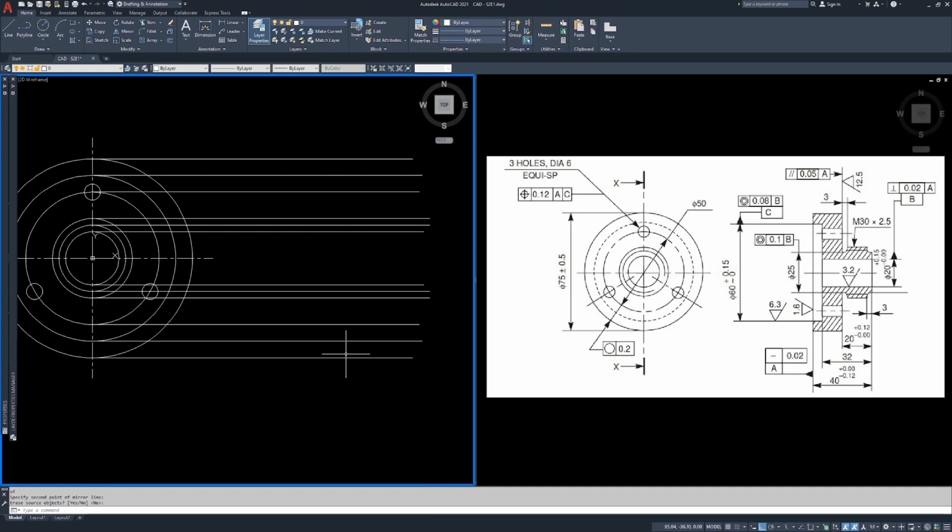So now, from these construction lines, we can actually build what we're seeing over here. So we need to start looking at some dimensions here. It looks like they're starting from the back. So all we need to do is just draw an arbitrary line in the back. Let's just draw a line just like that. L, right click, shoot a line back there. That's this back edge. So it looks like our first dimension in is going to be 3 units. So let's O, enter, or O spacebar, 3, enter. Offset that puppy in 3.